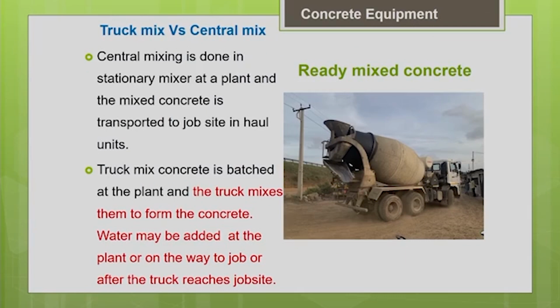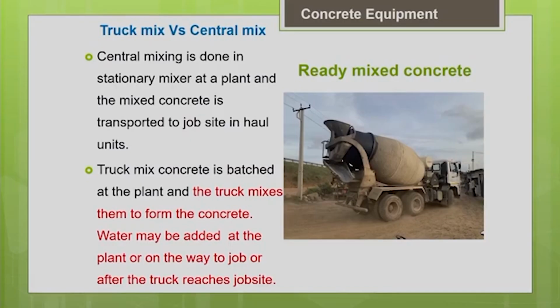Now we are going to discuss ready mix concrete. Nowadays we very commonly use ready mix concrete, particularly for works where the emphasis is more on quality. There are two different ways by which you can make ready mix concrete. These are the commonly adopted ways: one is truck mix and the other one is central mix.